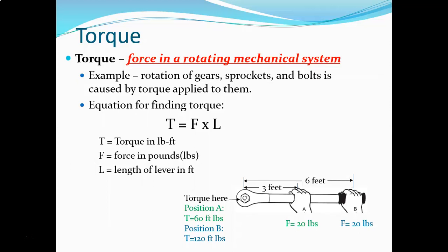So torque, I mentioned, is a force, but it's in a rotating system, a rotating direction. The example I like to use is torque wrenches. We've used those in the lab and in our last meeting for the hand tools section. So that's a good example of torque. It's a torque wrench and you're turning it in a rotating fashion. You can increase the amount of torque by increasing the lever arm. There's a formula to calculate your torque: it's your force in, how much you're applying, times the length of the lever arm.